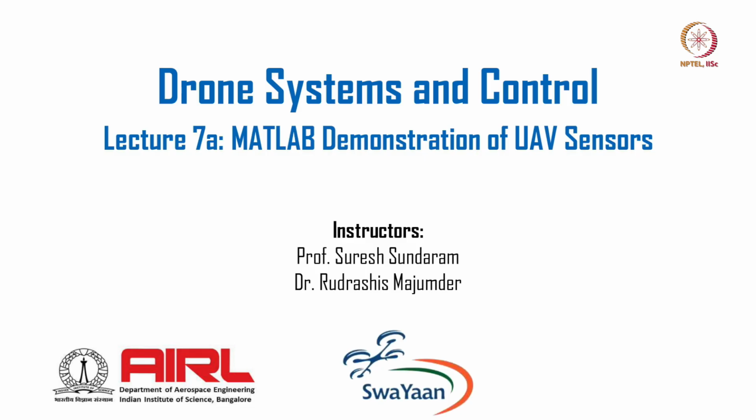In the lecture we discussed different UAV sensors available. One set measures the states of the system, right? So we have IMU, GPS, a barometer, or you can use single point LiDAR or radar to get your height measurements. Then you have other sensors which look at the context in which the UAV is flying. You could use 2D LiDAR, 3D LiDAR, 4D radar or even a camera to understand where the obstacle is, how far the obstacle is from the drone, what the relative position and relative velocity are. All this can be estimated.